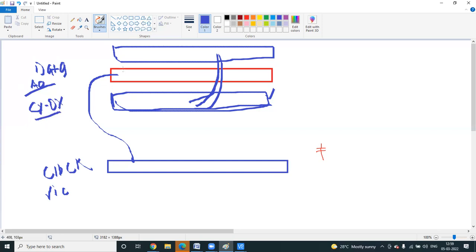So coaxial shielding means if it is M2, you will use the same material top or bottom, M1 and M2. If it is M3, you can use M3 top or bottom covered by M2 and M4. That is coaxial. For side one,